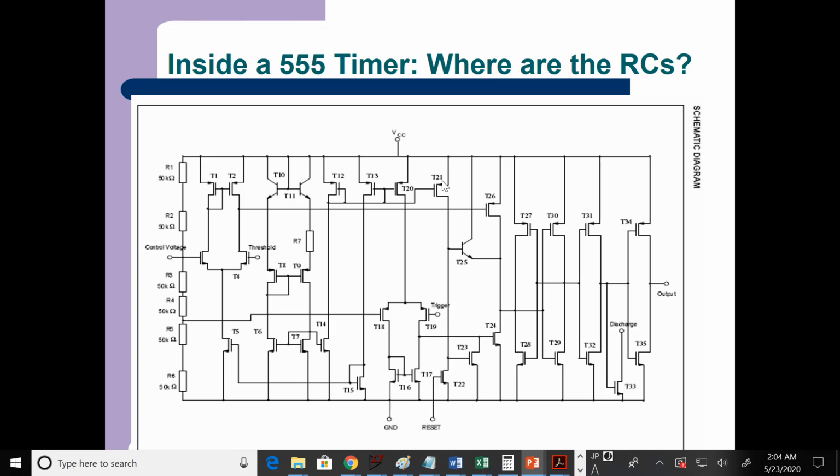So what you can do here is you have, which one was I using? I was using 26 and 24. So right here, let's say the input to 26 changes, this output will change. There's a bunch of capacitance on this node. Generally in LTspice or probably the other simulators you've used, you've treated this as an ideal wire and maybe not even thought about capacitance.